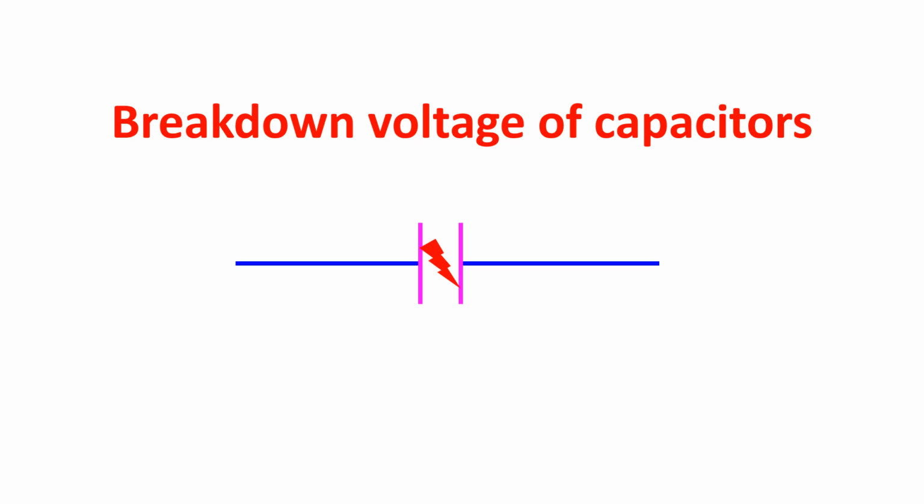At high strengths of electric field above the nominal working voltage of the capacitor, the dielectric separating the two plates of the capacitor might become conductive. This is known as breakdown voltage of the capacitor. Maximum energy which can be stored in a capacitor is limited by the breakdown voltage. The air gap between plates of capacitors used in high voltage vacuum tube circuits need higher spacing to prevent arcing. Capacitors with mica as dielectric between the capacitor plates have much higher breakdown voltages than air capacitors.